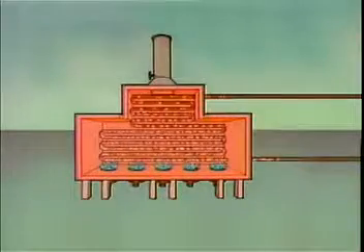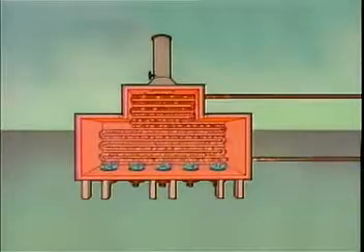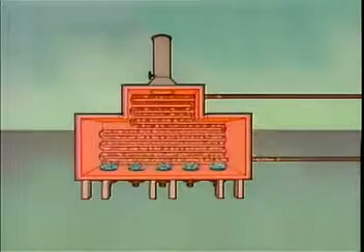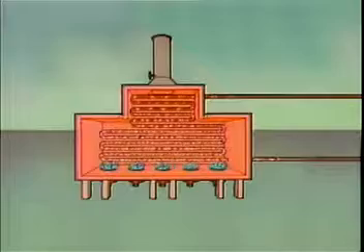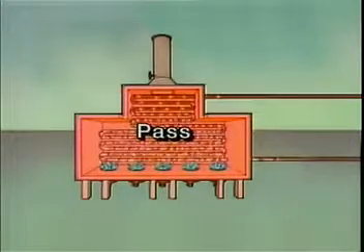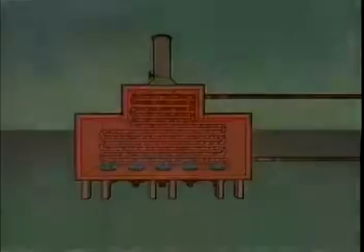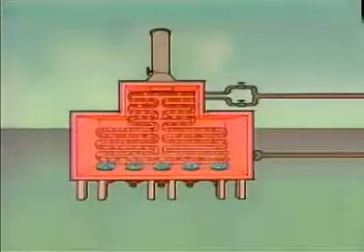The route that the process fluid takes as it flows through a furnace depends on the design of the furnace. Each continuous, uninterrupted path that the fluid takes is called a pass. This furnace is a single-pass furnace, but many furnaces are multi-pass types.